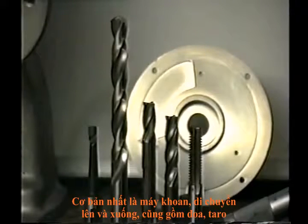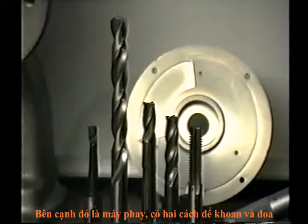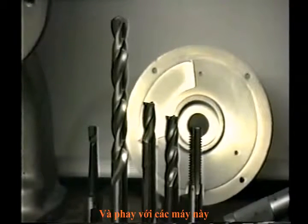It would also include boring, it would include tapping, and besides that we can do milling with small cutters with large cutters. So we have two things that we can do. We can do a drilling type of operation, an up and down type of operation, or we can do a milling type of operation. And let's take a look at some of the typical parts made in machining centers.